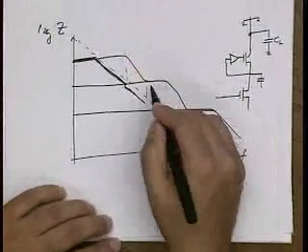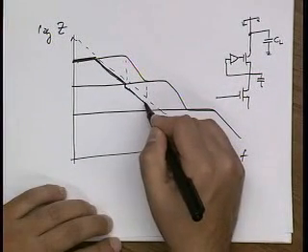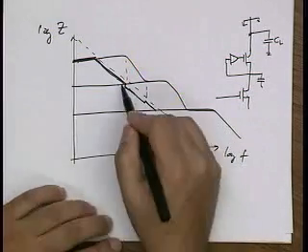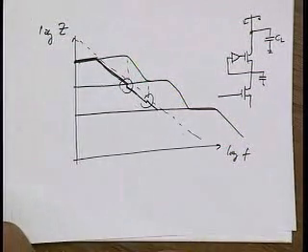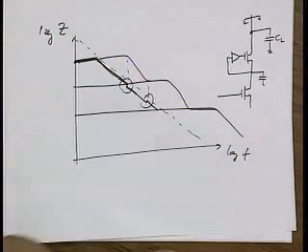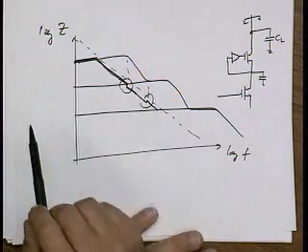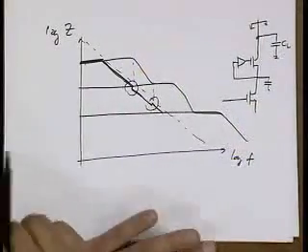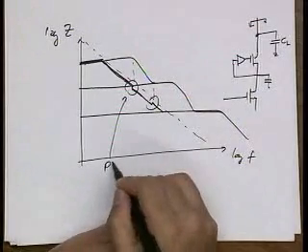As I come here, all of a sudden this impedance is holding constant. So there's a small shift. And these small shifts are actually imperceptible. If you plot them in SPICE, unless you zoom in really close, you won't see them. But they're there. And what these shifts represent are pole zero pairs, almost right on top of each other. So they're almost canceling each other out. And these are called doublets.